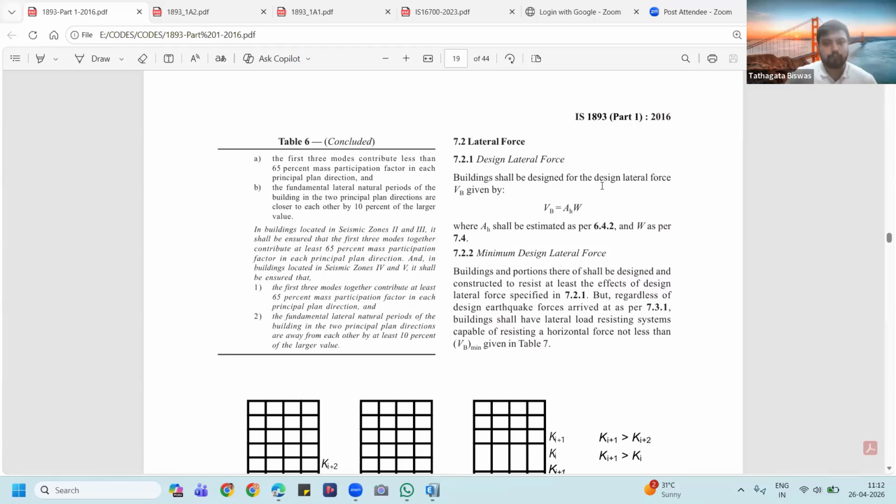We take the load of it. Okay, we take the load of that particular wall on top of the beam, right? So it means what? We are taking the load consideration, but we are not modeling the stiffness consideration. Okay. So there is a difference between load and stiffness. Stiffness means physically being present, and load means just the approximate load of that. Okay. So these two things are not the same. Okay. So how is this particular thing changing the concept of static analysis?